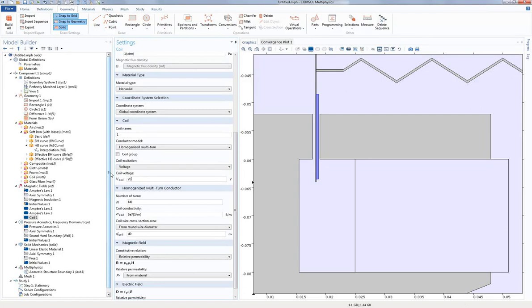Now let's pause for a second here. Pay attention to this, because if we were to type in just v0 like that, it would give us a permanent contribution, like the permanent magnet. So right here you would get a DC voltage applied to the coil. And that, of course, is not how a loudspeaker works. We want to drive it over a range of frequencies, so it should be an AC voltage.